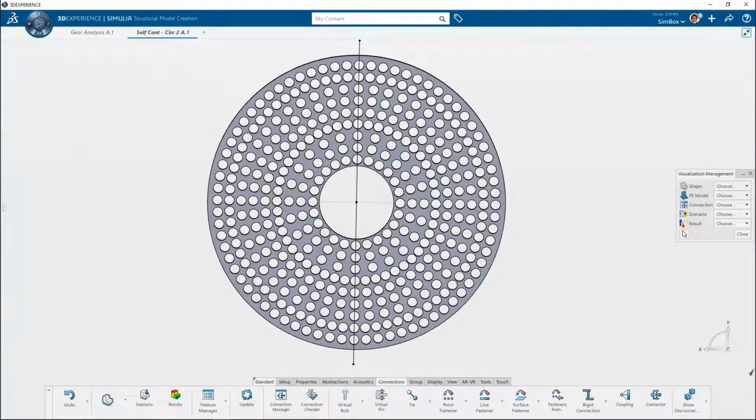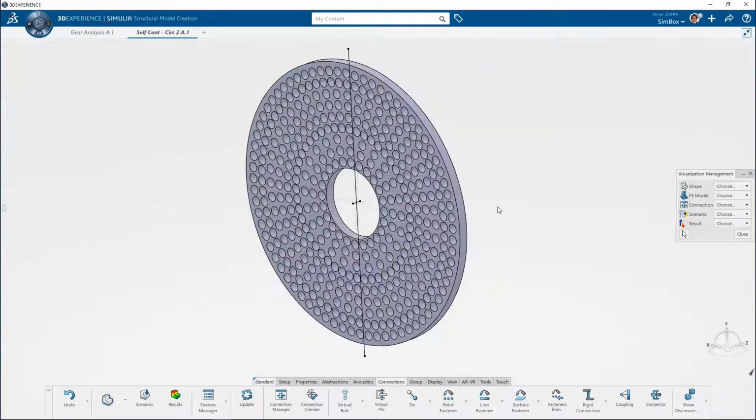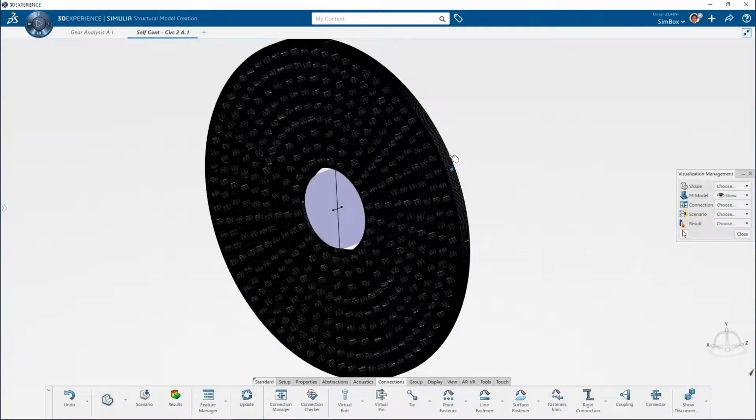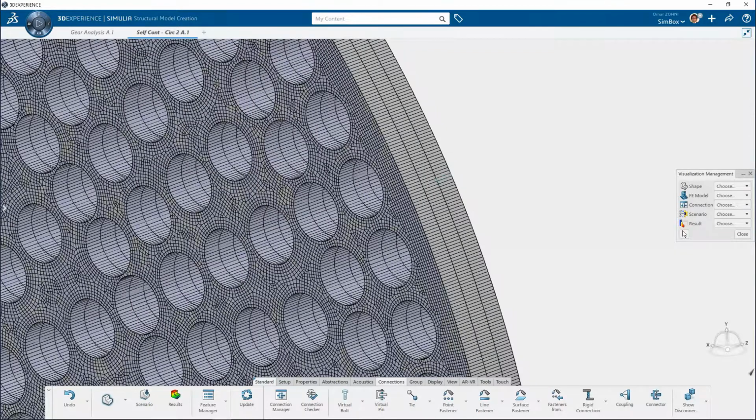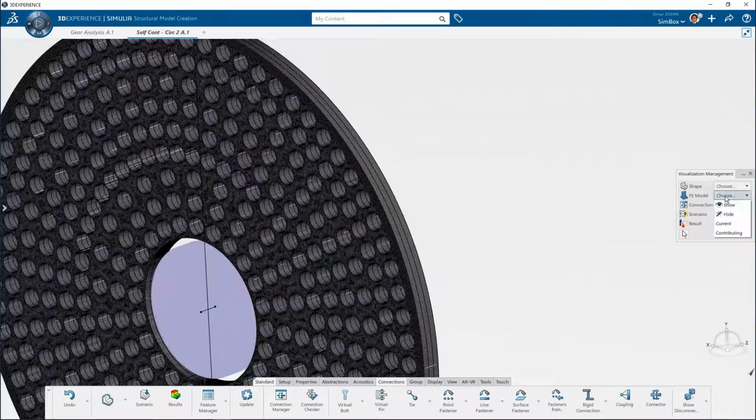Again, if you were modeling this inside of SolidWorks, you would have to go and specify the no penetration contact for all these faces. And, depending on the rotation and the displacement, I don't know that you would know what faces are going to be coming into contact. Another nice thing here, this model is very, very easily brick meshable. If we just take a look at the finite element model, and I don't want to spend a lot of time here, but obviously it's a nice, well-structured brick mesh with 3 elements through the thickness. Could have put more elements through the thickness if I wanted to.